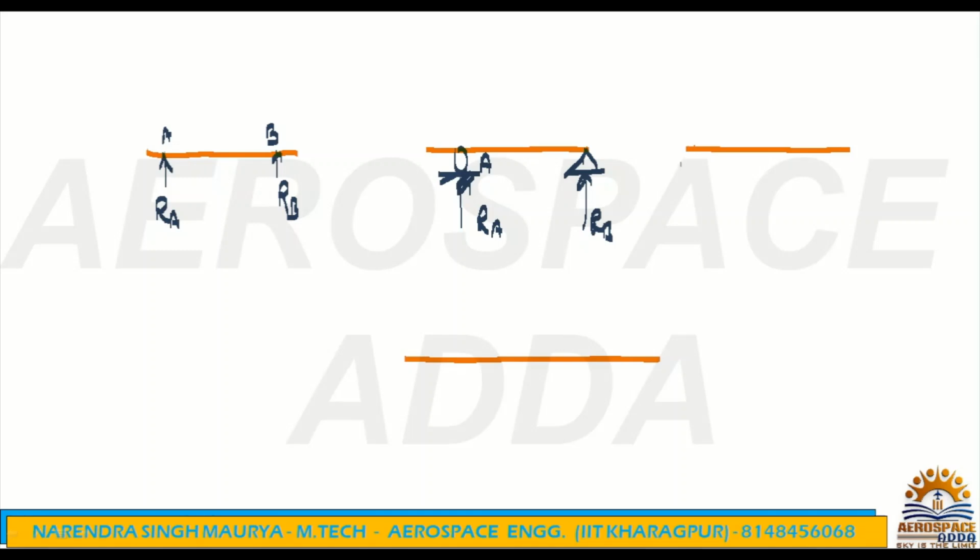If this is the hinge support, how will you show the hinge support? I told you, you can show the hinge support by a dot. This is the dot, so this is the hinge support. So here also you will get a reaction force, one vertical and one horizontal. Similarly here one vertical and one horizontal.